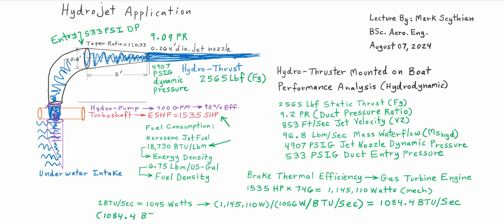But then we have to account for the actual fuel consumption, which is then rescaled to the thermal efficiency and its reciprocal. So 1 divided by 0.4 is 2.5 times more fuel consumption than what we get at the output drive for useful or usable mechanical power or brake horsepower.